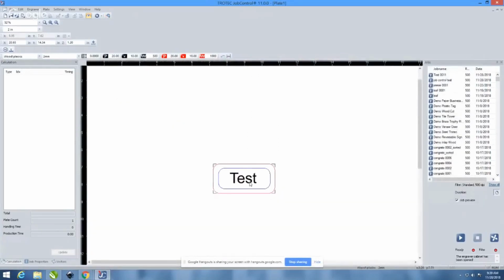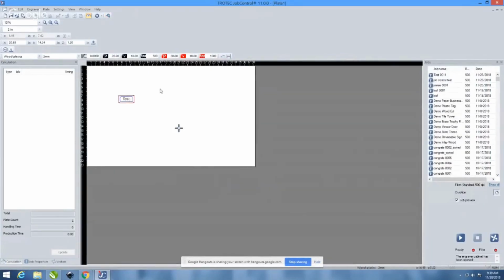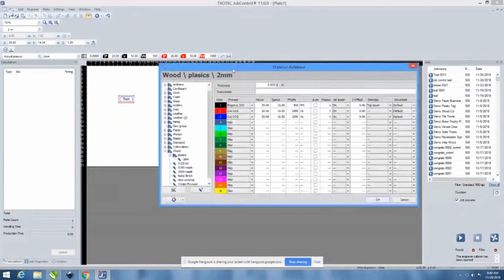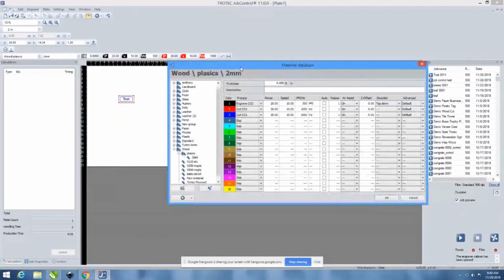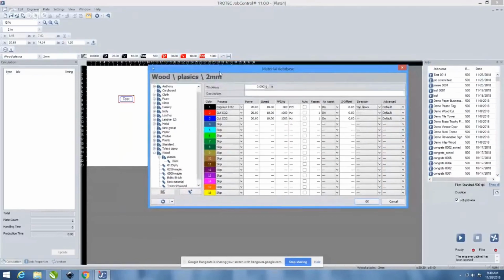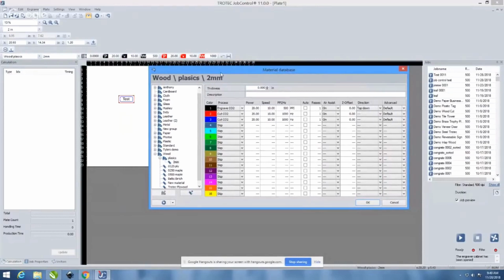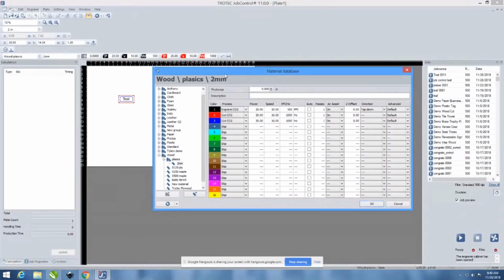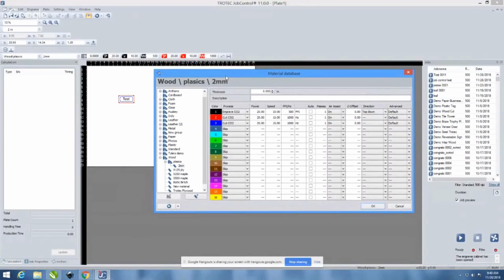And now we can see our blue line here. I should also quickly mention a lot of issues I had when I first started using the laser. I kept forgetting, when I did the cuts, to set the line to the thinnest line. So in Corel, it's a hairline, and in Illustrator, it's 0.01, I believe. Is it 0.01 or 0.1, Anthony? I can't remember. 0.01. When in doubt, just go smaller.